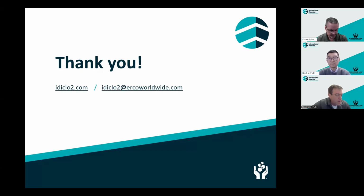But still grabbing a sample, probably using ion chromatography for the low amounts of chlorite residual for monitoring your MCL is probably the most reliable method. The Palin test and other amperometric devices can be used, but require some experience with the analyst to make sure you're getting repeatable values. Those tests are mostly for chlorite residual analysis. Some of those can also do chlorine dioxide residual.